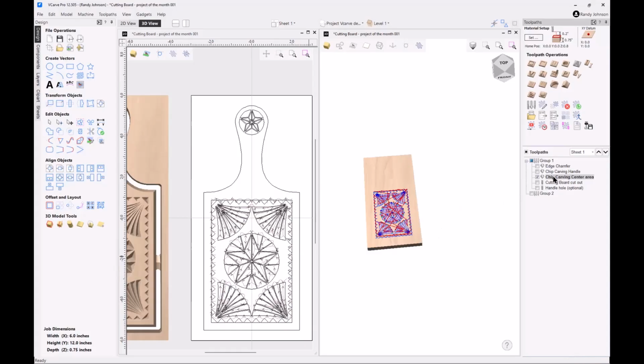Because when you select the toolpath right here, it shows you the associated tool vectors. But something got disassociated here. I'll show you an example. So if I go up to this one, notice how when I highlight it on the right, these turn pink on the left. That's because it's telling me which ones are associated with it.